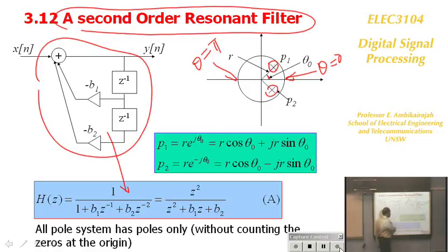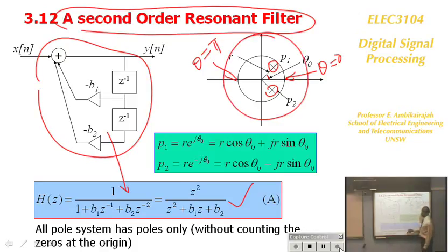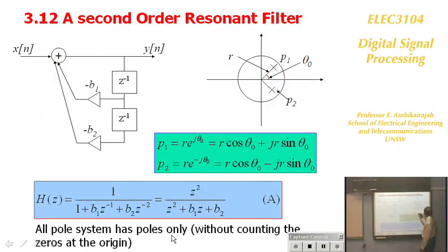That's y. And if you simplify, that is your transfer function of that system. Let's write that from the pole-zero position, this is only a pole, write the transfer function for that. Which is easy because all we need to do here is find out, if this is r, this is cos theta, find out that value.